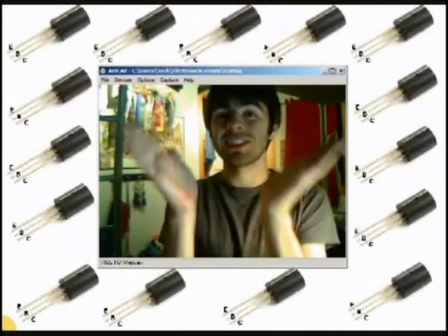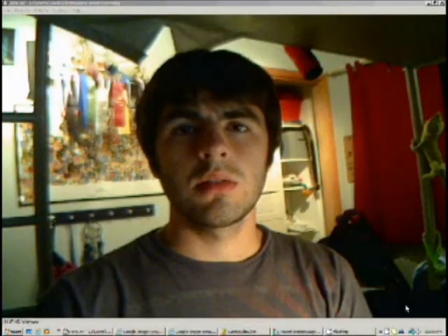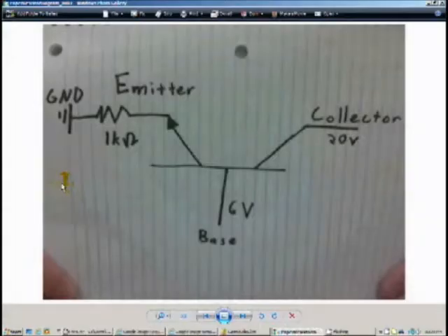First I'll explain what a transistor is. A transistor in a circuit looks like this. You have your base B, your collector C, and your emitter E. The base controls this big flow of current through here. It could be something like 2 amps, but this 2 amps is controlled by just this tiny bit of current from here. This could be like 2 milliamps. This 2 milliamps is controlling all the 2 amps that is flowing through here.